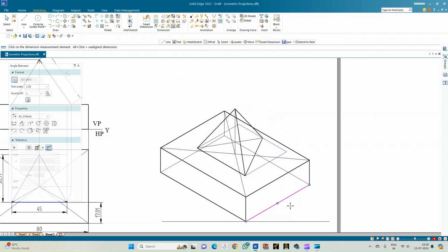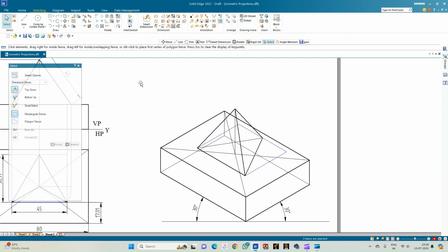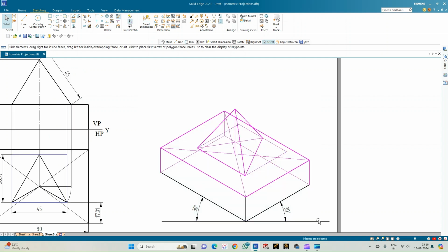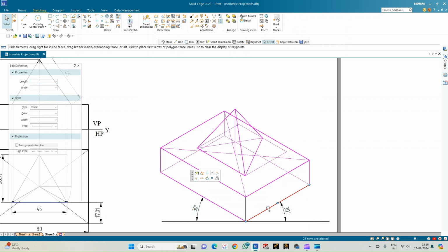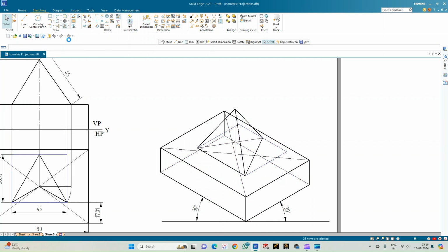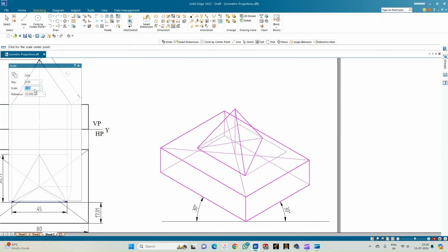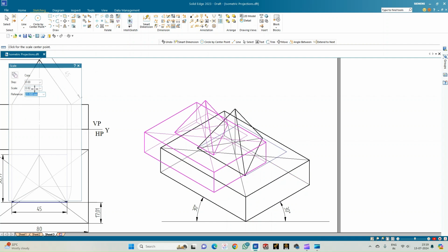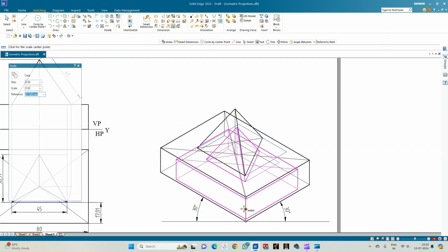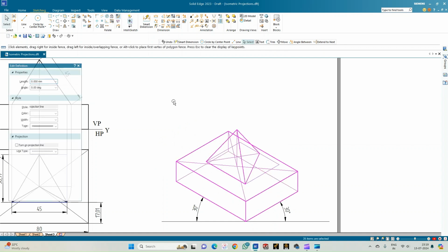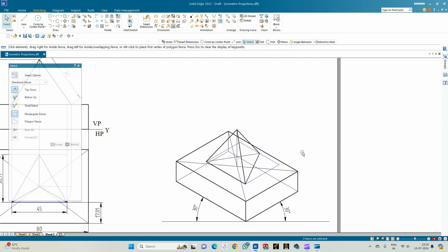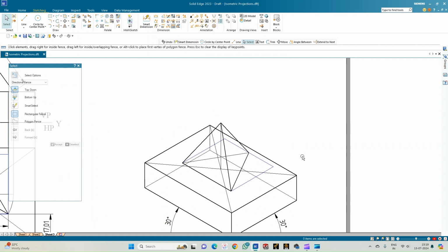So go for the angle between. So this is 30 degrees and this is 30 degrees. So this is in the actual scale. So now select the entire combination of the solids and then reduce the scale to 0.816. So this is a very important step. So go for the scale option, change the scale to 0.816, the original dimension, and ensure the copy is off, and then place it at the same point. So you get the actual isometric view of the combination of the solids.